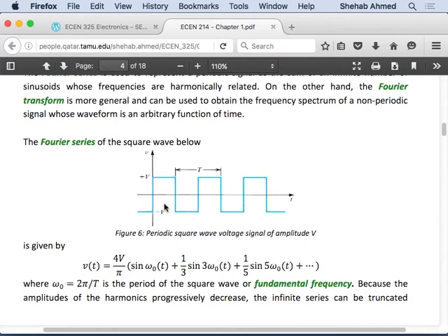If my sensor is producing something like this, and I want to send this to my signal conditioning system, my processor, how do I do this? I have to pass this to the amplifier. The amplifier now needs to deal with frequency content in all this bandwidth, right? So let's say I have to filter, I have to amplify. Can I filter content that is useful?